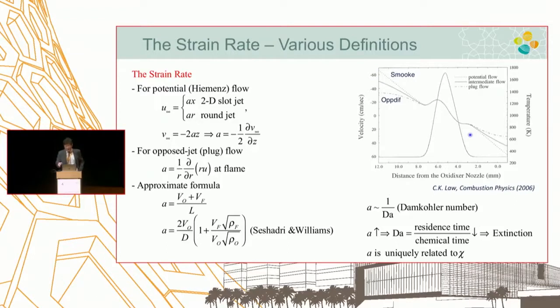Those are minor details, but the ultimate message is that this overall slope determines the flow residence time, which we now commonly call strain rate, and that is directly related to the Damkohler number. Increasing the strain rate will reduce the Damkohler number. That's a nice way of reproducing the S-curve turning point. You can start from the frozen solution to ignite. You can do the extinction experiment, and those are all done in this counterflow burner.